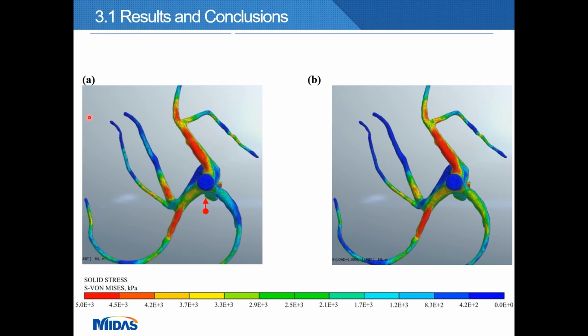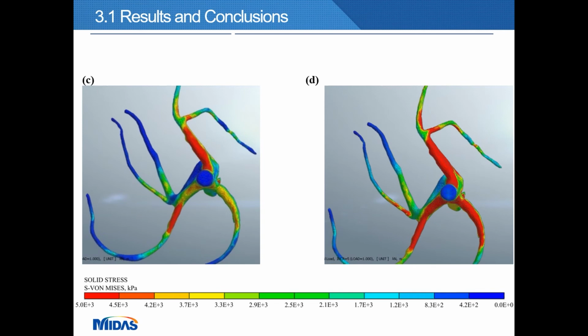For the Samanea saman, the root-soil interaction behavior also highlighted that an increase in soil stiffness, based on the soil Young's modulus, can cause the stress at the base of the trunk to increase, especially on the tension side. So we analyzed 4 conditions, considering the matric suction and its influence on the elastic modulus of the soil. Analysis A considers a first stage with the lower E modulus, and condition D is the higher E modulus. Every time we increase the elastic modulus of the soil due to matric suction and rainfall, the condition of the tree changes.